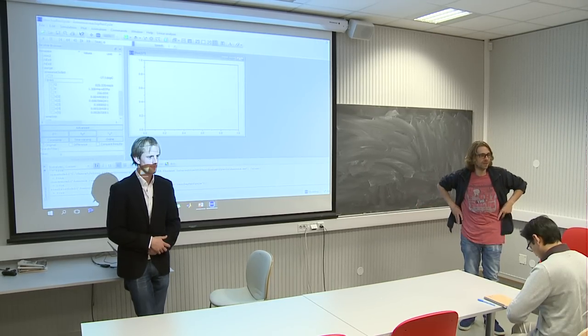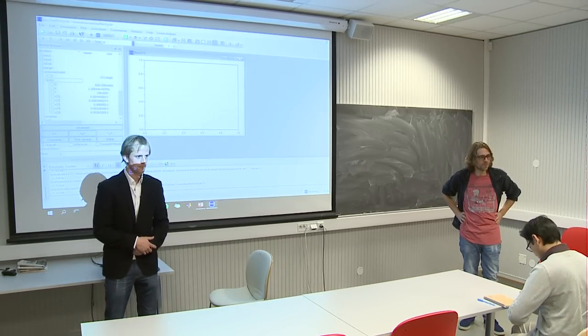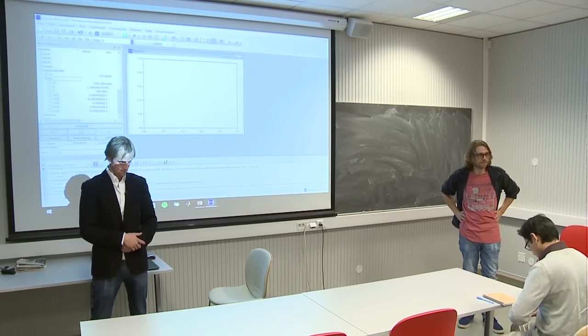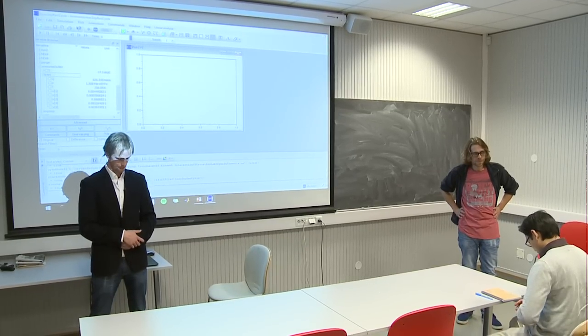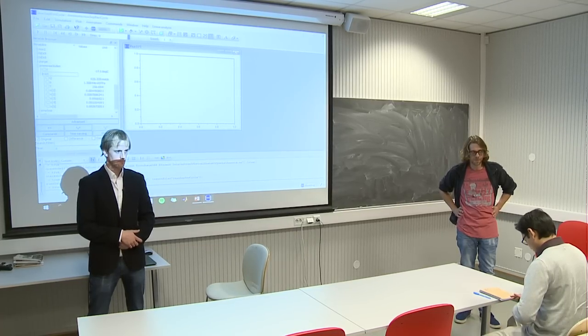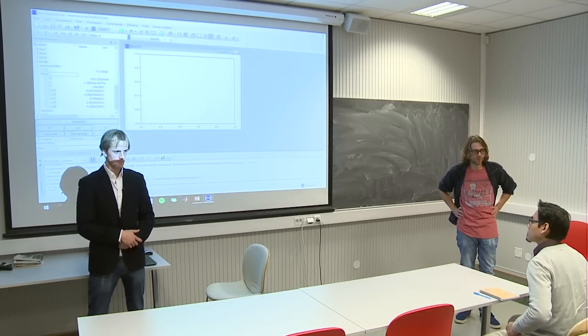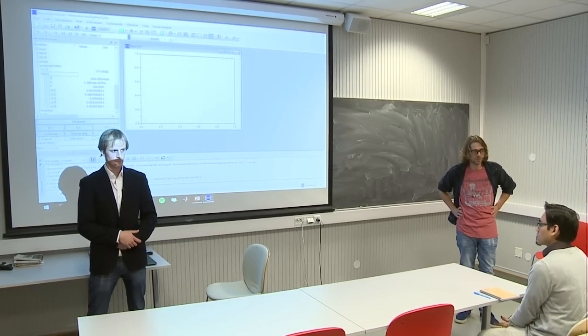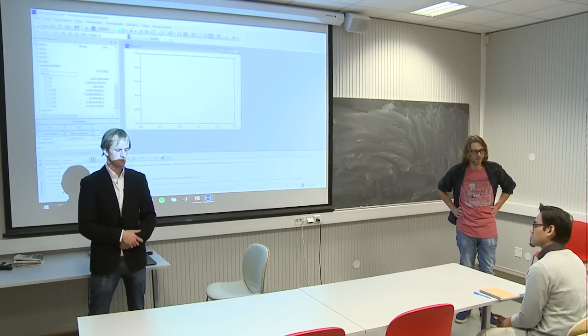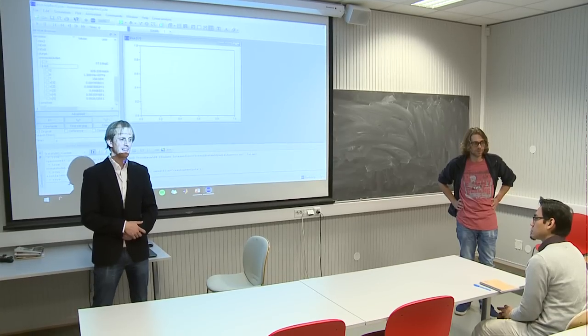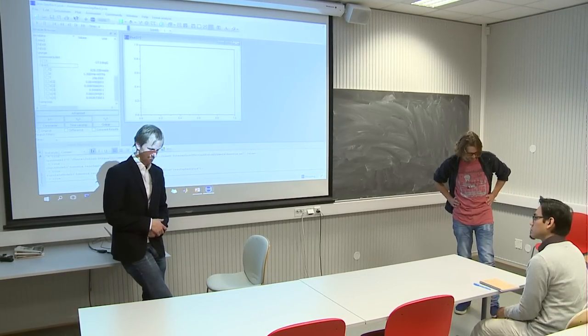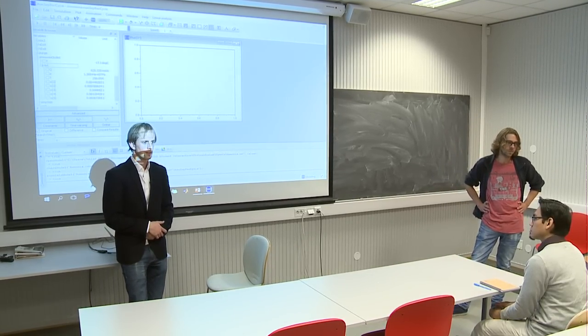Modelica is an equation-oriented simulation language, isn't it? You solve all the equations simultaneously. Yeah. And that's the reason why I think it's also difficult to converge steady-state solutions? You have to have a good initial guess in order to have convergence. Exactly.